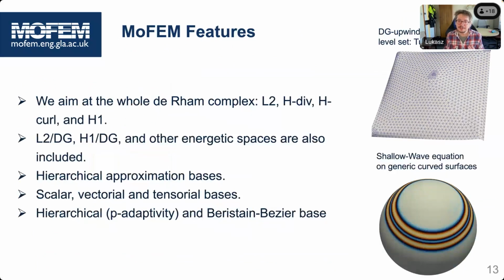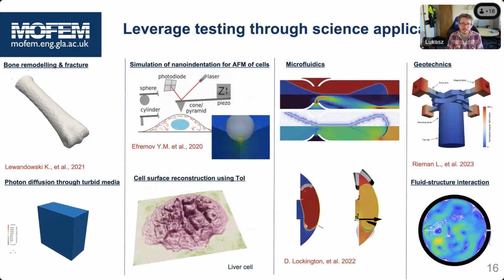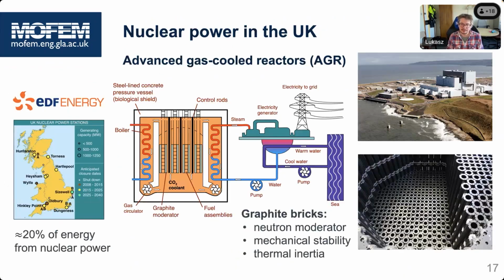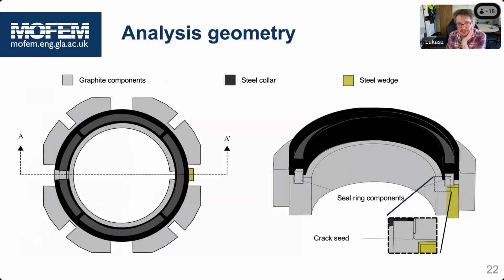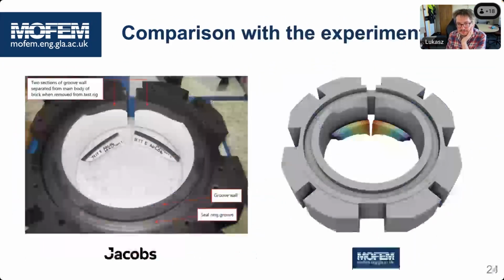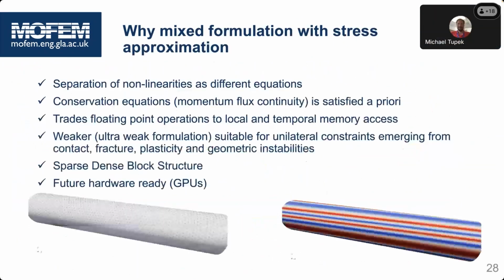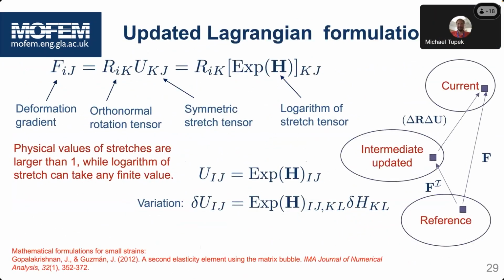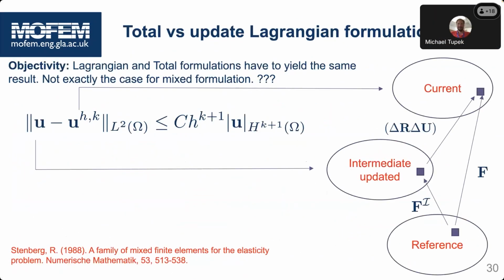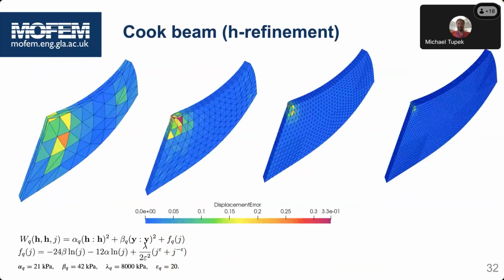So it's kind of killing several birds with one stone, thanks to the hybridization and the separation of the nonlinearities you have with this approach. When this criterion is reached, you essentially measure the Griffith energy you dissipate on that surface, and then you break that space.